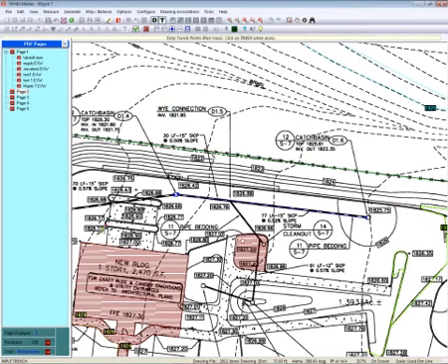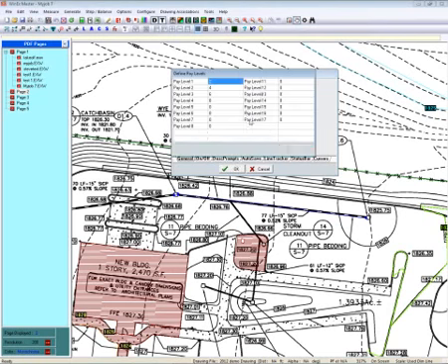And when you're all done laying out your pipe on the whole drawing, just come up and click on Finish. We'll give you not only the length of the trench, we'll give you the volume. We'll even give you, if you checked on that native fill button, and in your area, this trench is going to be open for several days in inclement weather, we'll tell you the square footage of that native fill. So if you need to go out and get some plastic sheathing or some other material to protect that fill from washing in, you'll have that. You can even go up to Configure and go to Default Settings, and you can go in and define different pay levels depending on the type of depth you're going through or the strata you need to cut through, however you want to set that up, and that will show up in your report.